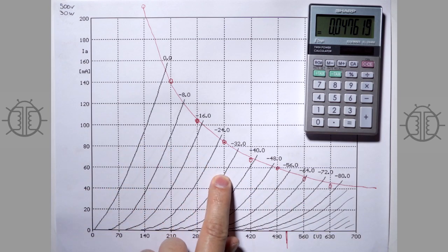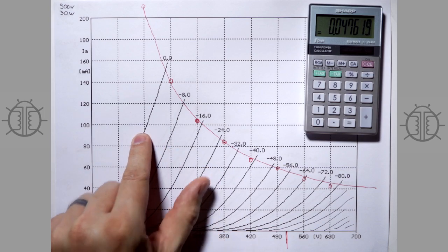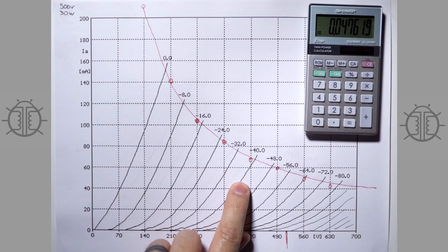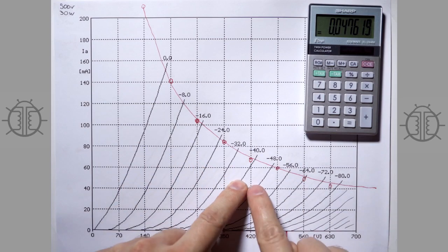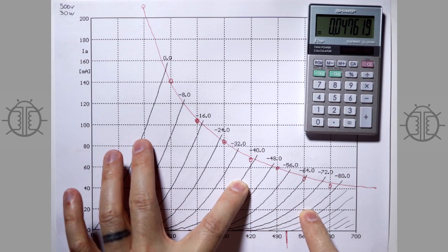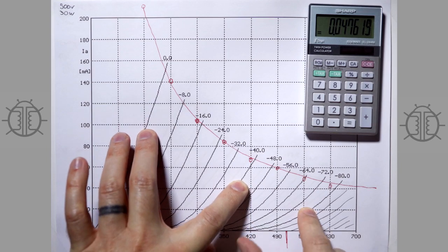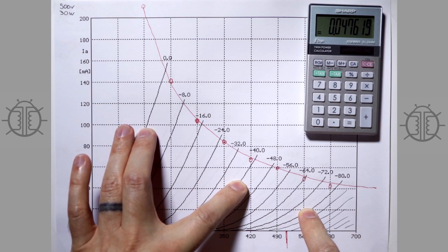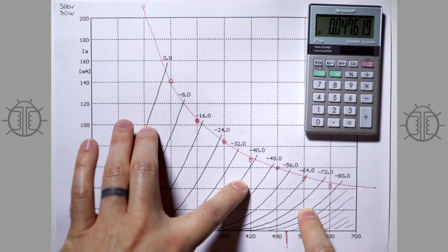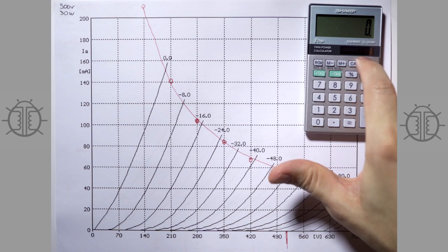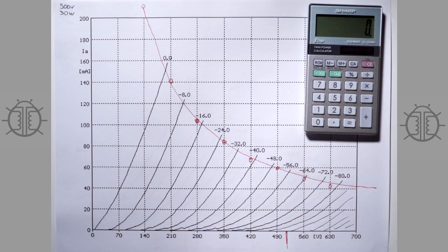Let's say we put it here, we've got 1, 2, 3, 4 here, and we could go 1, 2, 3, 4. That's not so bad. Or we could go up to here and go 1, 2, 3, 4, 5, and 1, 2, 3, 4, 5. Now you're getting some distortion there, because you swing from here to here, that's a lot more voltage than from here to here. So you have a trade-off between power output and linearity. I should talk about power output, because what we're trying to do with an output stage is create power, right? With the driver stage, it's less about power and more about voltage gain and output impedance.